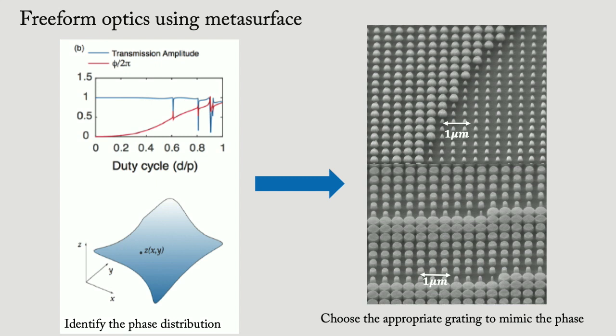So when you fabricate this structure and design, this is how it looks. You can see the scatterers, the lateral size is changing, and each of the scatterers gives me some phase shift at that XY location. Interestingly, you can see we started to make a cylinder, okay, and we get something that doesn't look like a cylinder. And it still works really well. And that's another reason why metasurface is so popular: one of the criticisms of nanophotonic structures has been that it's extremely difficult to fabricate.